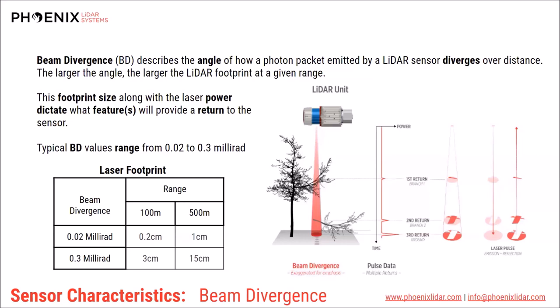You can imagine this image in the beginning or in the middle, a very tight cone here would largely skip much of the branches, especially in the leaf-off type of application, as well as the pulse repetition rate in combination with this tight beam divergence can help penetrate vegetation and preferentially capture the ground.